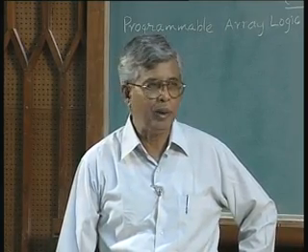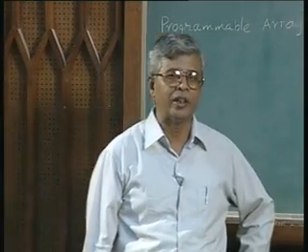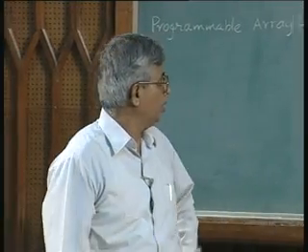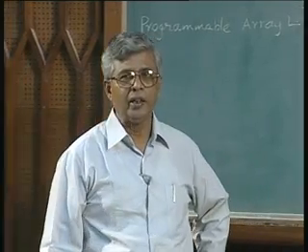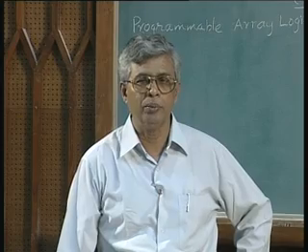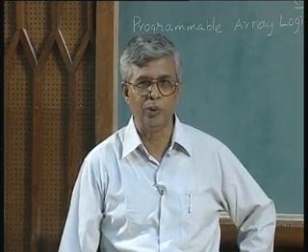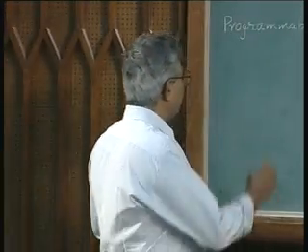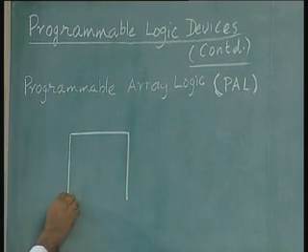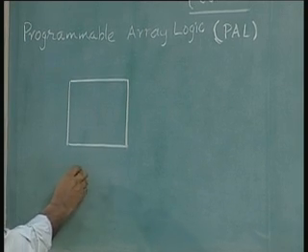But what is different between PAL and PLA is, in the PLA we had the OR gates in which we can combine the product terms whatever way we want. On the other hand, in PAL the OR gate connections are fixed. You have no choice on what product terms are going to make a specific output function. So, here we have a slightly varied version of the programmable logic array. This is the PAL structure.